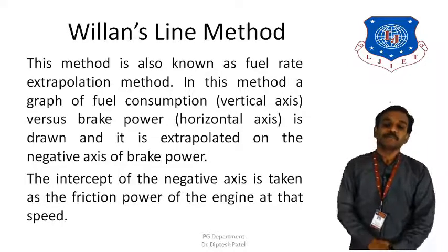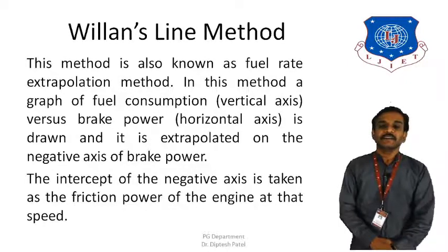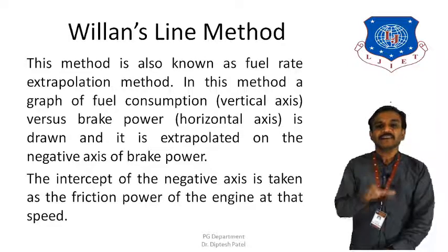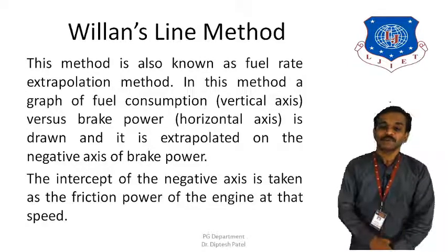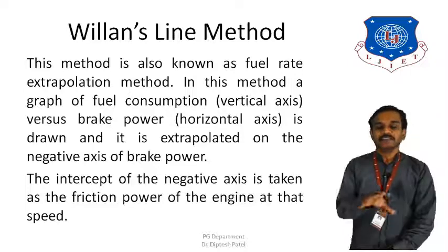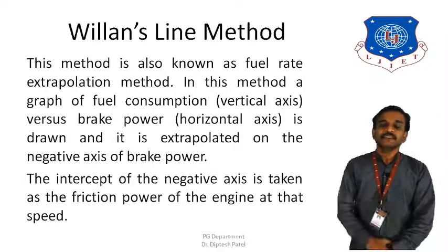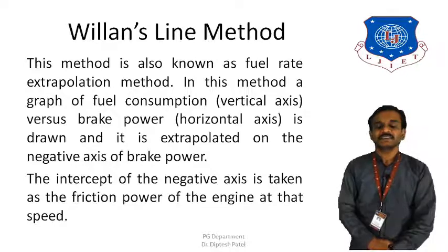In the simple motoring method, the engine is operated with the help of an electric motor, and it is run for a little while to maintain a constant oil pressure and a constant cooling system temperature, due to the frictions. Then after a certain period of time, the power being delivered by the motor is measured, and that is the friction power. So this is how you can simply measure the friction power, and that is known as the motoring test or motoring method.